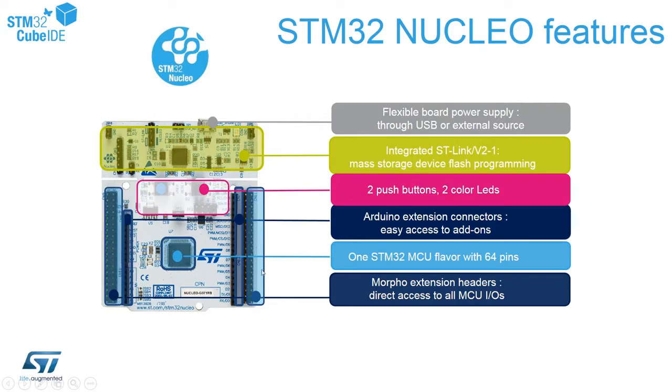Below you can find a dedicated board for the microcontroller. Our microcontroller would be STM32G071RBT6, a 64-pin microcontroller from the STM32G0 family. This is the central chip on the board. On the board you can see as well some additional components which would be useful for us: some buttons, LEDs, a jumper to measure the current consumption, and some connectors which allow us to connect other components.